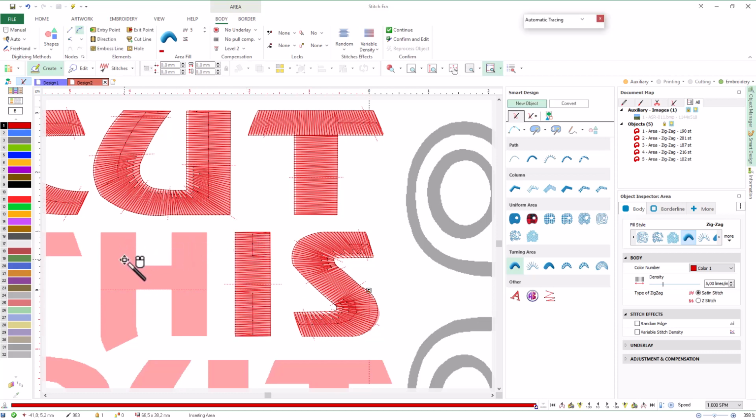This region of the image, the letter H, presents a situation similar to that of the letter T. Here we should use 2 cut lines to divide the contour into 3 contours, one for each vertical region and one for the horizontal region. However, we will use a more automated auto trace mode, called auto-complete. Select auto-complete and click to capture the contour. Note that the definition of geometric elements is disabled in this mode. Press enter and the system will complete the creation of the object.